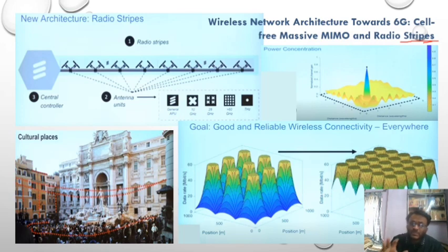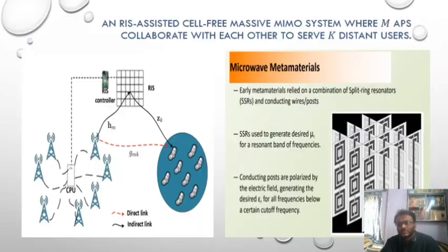Even the size of the antenna can be a concern. If you consider higher frequencies, antenna size will definitely decrease, because we know the antenna size is about lambda by 2, for printed antennas. Whenever we go to higher frequencies, meaning millimeter wave and terahertz communication, the efficiency of the antenna and the coverage area also decrease. Another thing is that the combination of these antennas basically makes arrays, so there are some peak positions as well. Non-linearity in the receiver amplifier is another problem, so we can stabilize it over this channel cutoff.